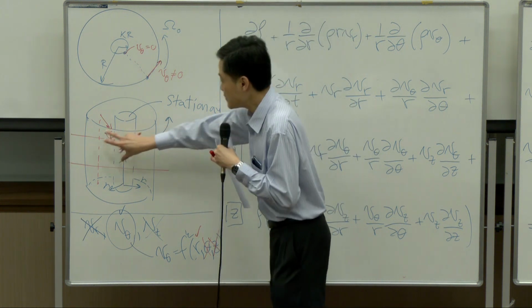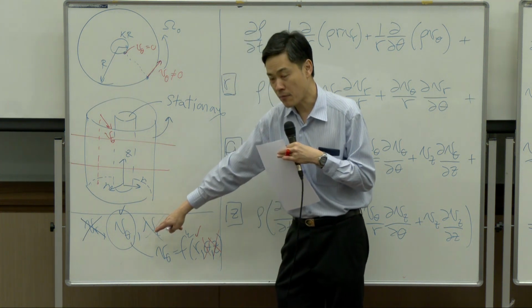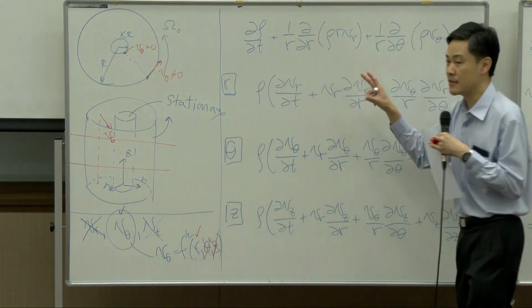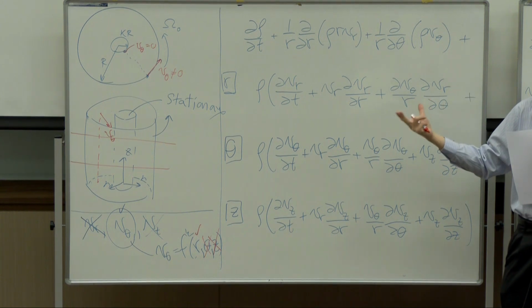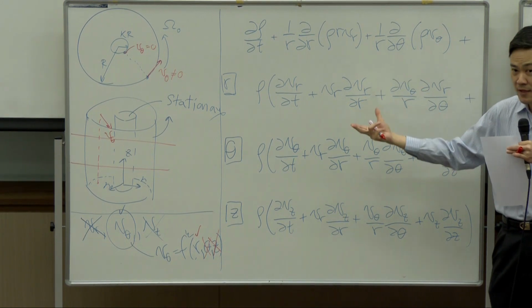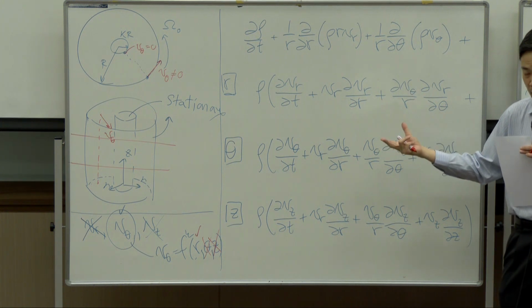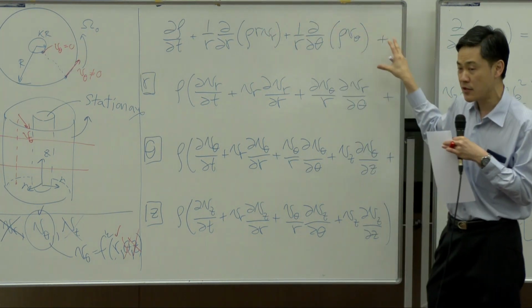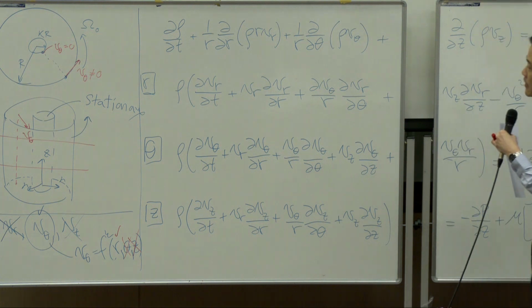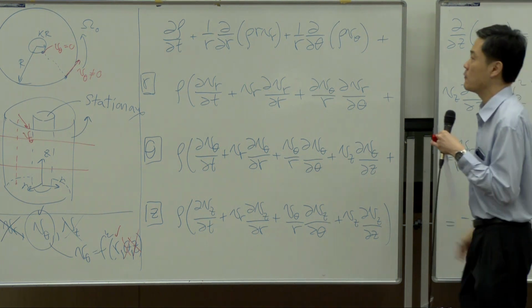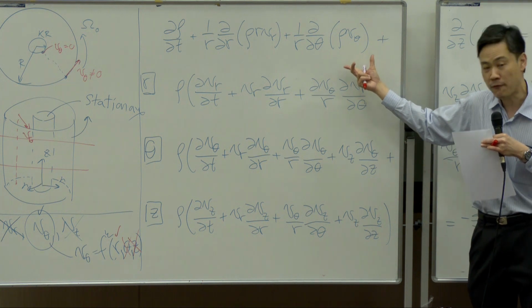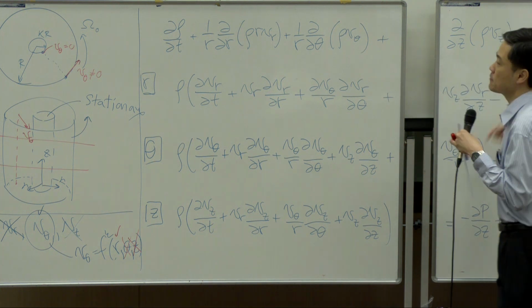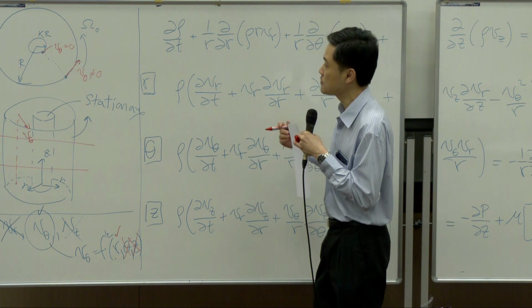Now, once you already determine the non-zero component of velocity and determine its function, next step, as I said, when you do the momentum problem, if the system is pure species, isothermal, then it would be suggestive to start with the equation of continuity. This is the equation of continuity in cylindrical coordinates, without assumption of incompressible fluid. This is the generic form. If you start with the generic form, you can just eliminate terms that are 0.